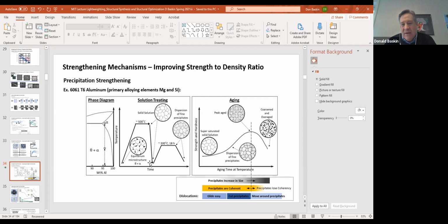We get this part back, okay, and then all of a sudden we start having failures. These motors are blowing apart, and we don't know why. It turned out that when they were heating the housings up, the people doing it were letting them sit in the furnace at maybe 80, 90, 100 degrees Celsius for up to 6 hours. For some reason, this motor company didn't really know that they could destroy the aluminum by doing that.